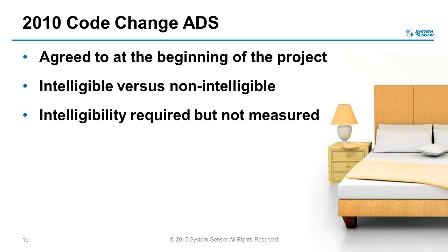For example, if an expected ambient noise level in the ADS will be virtually impossible to meet intelligibility, then the designer can decide that ADS does not need to meet intelligibility. This approach avoids costly over-designing of voice evacuation systems, especially in areas that are impossible to meet intelligibility. In this case, the designer may decide to use a different type of notification appliance to meet the code, such as, just as an example, a strobe.